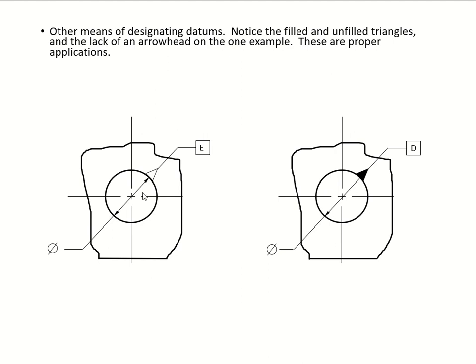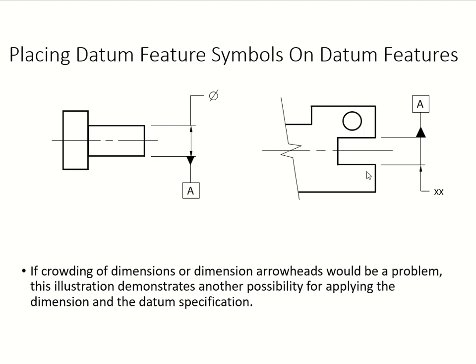So just showing you the dimension of this circle diameter. Look at this, the diameter. Here, filled. See these little arrowheads right there, two of them, and here filled. It just goes from the surface, circumference, which is the base of this filled triangle of your datum feature control right there, and goes all the way down to here. See, there's only one arrowhead. So pay attention to these little things when you draw. Going back to the previous example, here is just a regular extension line, dimension line in, dimension out.